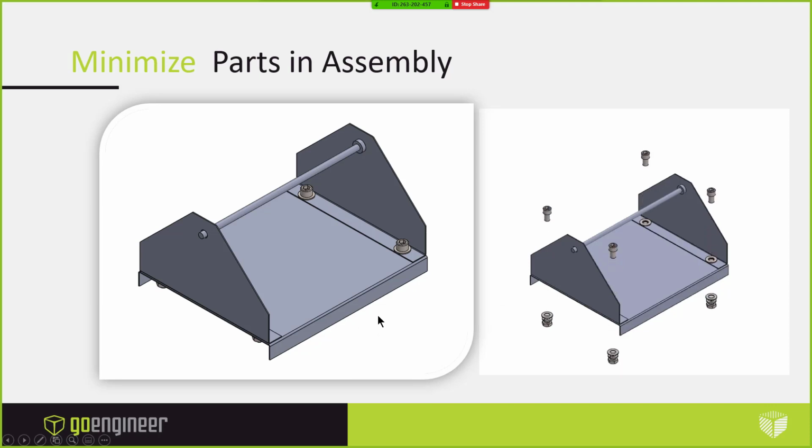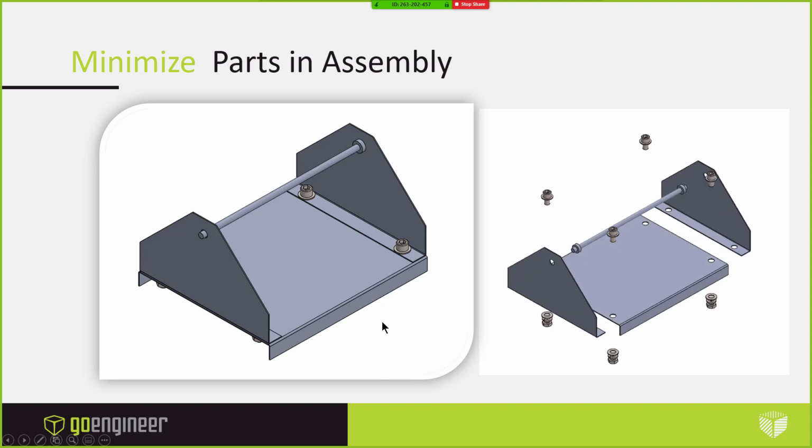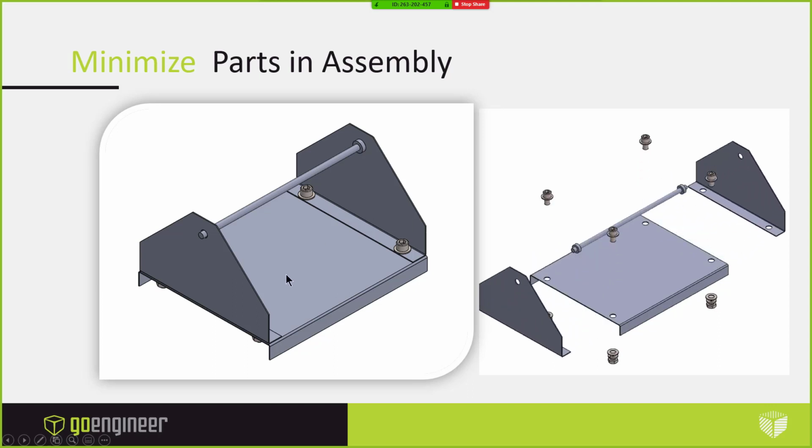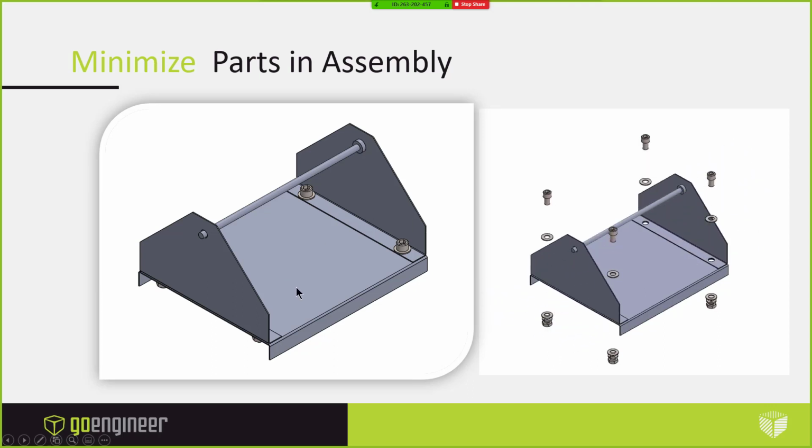So I got this little example of a roll bar assembly that I created, and it consists of 24 different parts. Between all the fasteners and the side pieces and the bottom, you can quickly see that this is going to take some effort to keep on your shelf. You're going to have all these sheet metal parts. You're going to have to reach out to somebody who's going to cut them, shear them, plasma cut, water cut, some vendor that's going to make these 3 sheet metal parts and then also bend them for you.